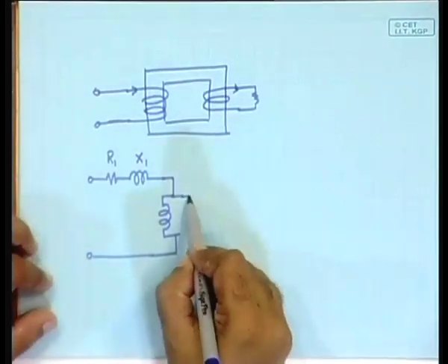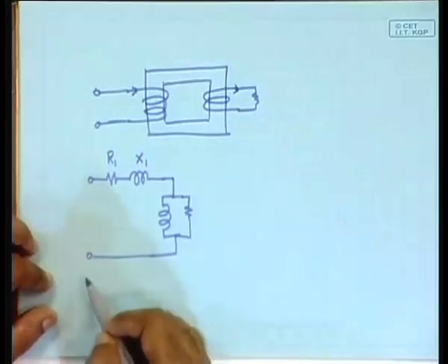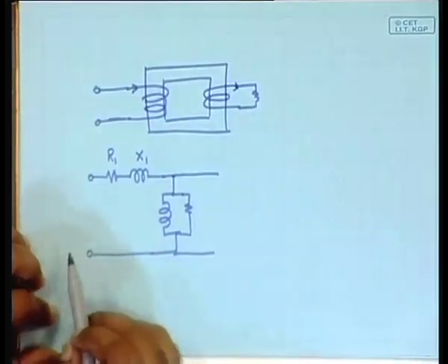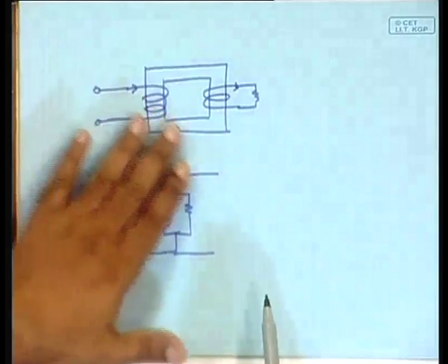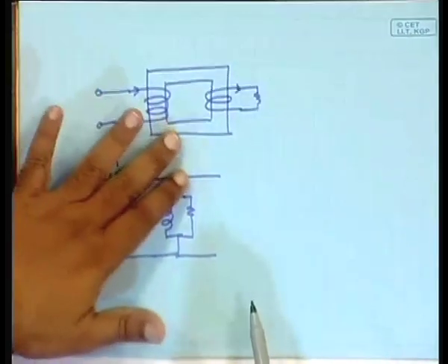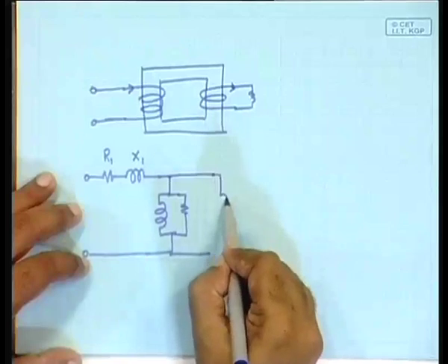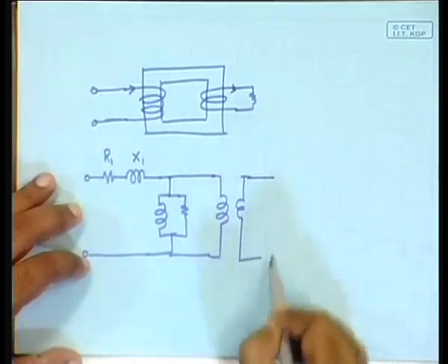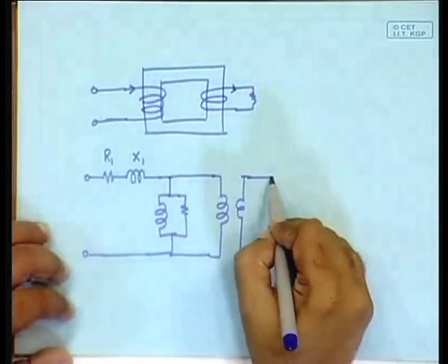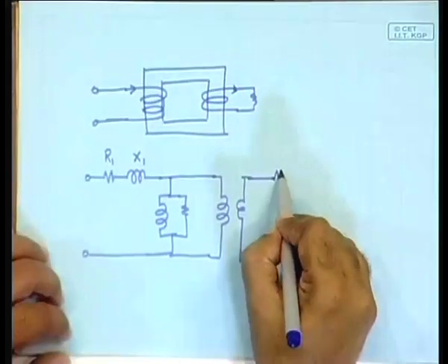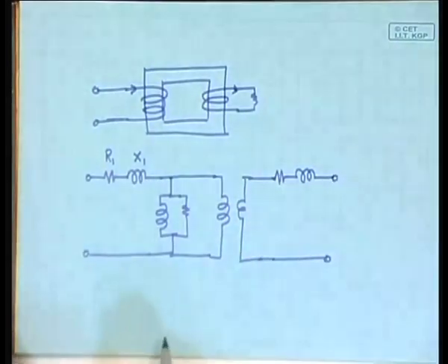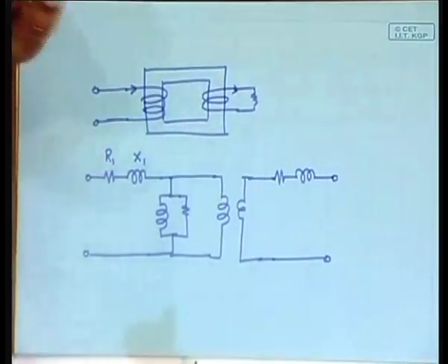So that is represented by a resistance here, and then we would say that now it goes to the secondary side, and then we have represented all the non-idealities, and then we would say that here let there be an ideal transformer now, and on this side there would be a resistance and there will be an inductance to finally give the output.